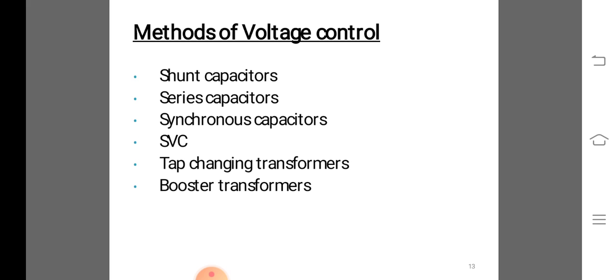The capacitor bank often includes, in part, harmonic filters which prevent the harmonic current from flowing in the transformer and the high voltage system. Filters for the fifth and seventh harmonics are generally provided. The thyristor controlled reactor, TCR, is operated on the low voltage bus in another form of the compensator. The reactor compensator is connected to the secondary of a transformer.